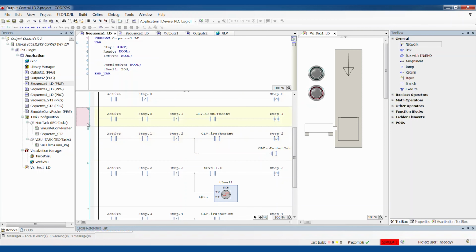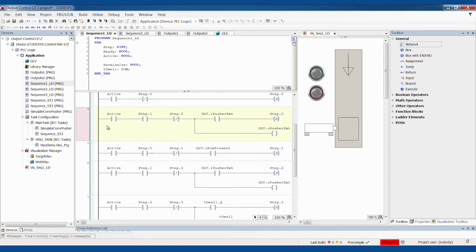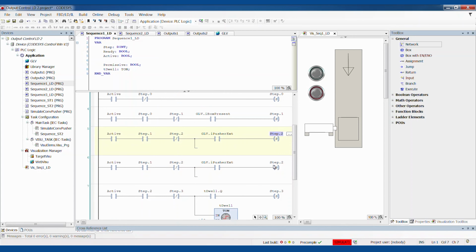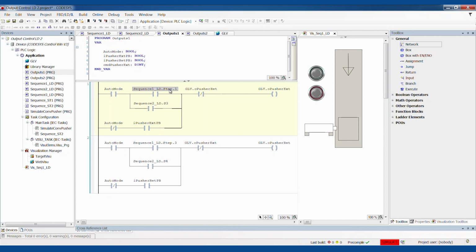Okay, well, I can copy paste this rung here. This step now, maybe it used to be 2 and now it's going to be 3 or something. So not only do I have to update that comment, but I have to come over here and update that step from 1 to 2, 2 to 3, whatever it is. So it becomes a multi-step process. So right now, this is not concise or labeled.